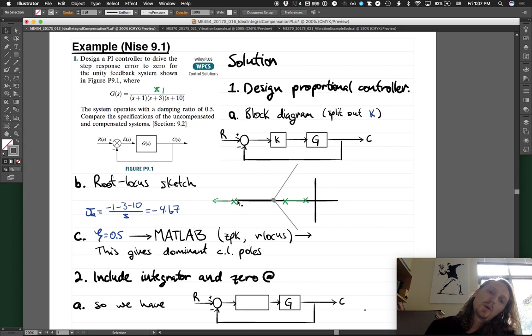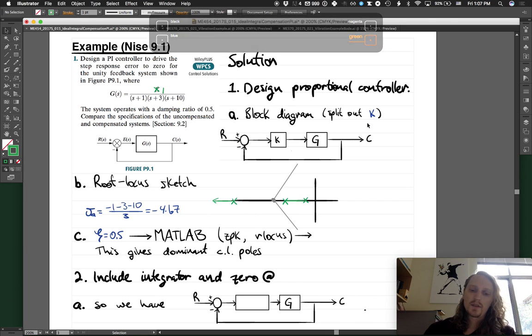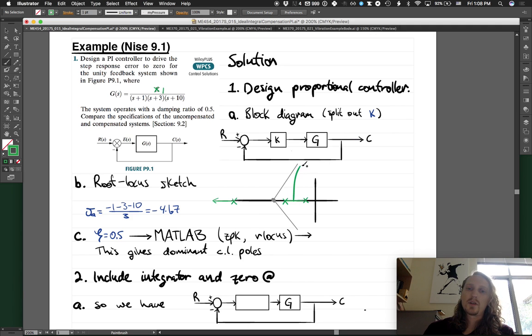See that this pole is definitely going to follow that asymptote off to -infinity, and these two are going to split off the real axis, and we can find out where they split off, but I'm not going to, just for the sketch. It's probably not going to angle back like that, they're going to approach these asymptotes, so something like that.